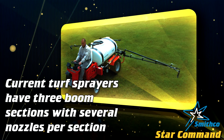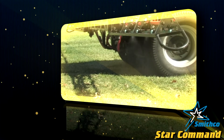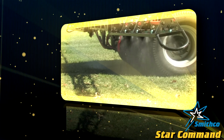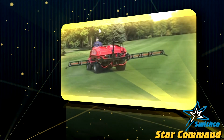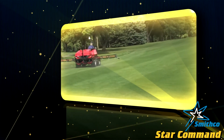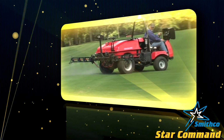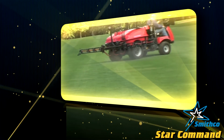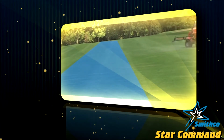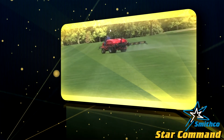Individual nozzle overlap control. Current turf sprayers have 3 boom sections with several nozzles per section. Sharpshooter with Invisio Pro and Switch Pro provide 10 sections, allowing the possibility of individual nozzle control. With this technology, individual nozzles will now automatically and instantly shut off as the boom passes over areas that have already been applied. It automatically and instantaneously turns the individual nozzles back on when it encounters unapplied areas. Finished passes or skips can be sprayed with only the individual nozzles required for complete coverage.